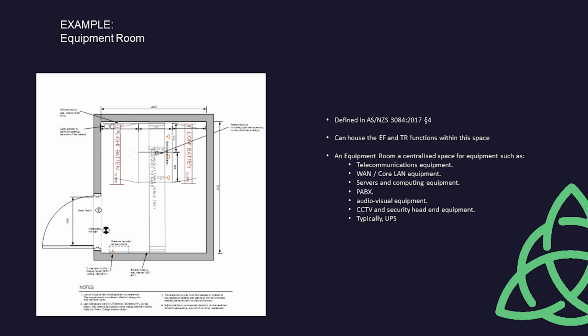To circle around to this again, the air supply must be fitted with filters to allow an ingress protection rating of IP54 to be achieved for the room air supply. At least 2% of the total air moved must be fresh air. The supply air discharge velocity must not exceed 6 meters per second. The air conditioning must be provided to meet the local peak solar load. Additionally, when peak outdoor ambient conditions are reached and maximum equipment rack load is achieved, the supply air to the front of all racks must not exceed 25 degrees Celsius.